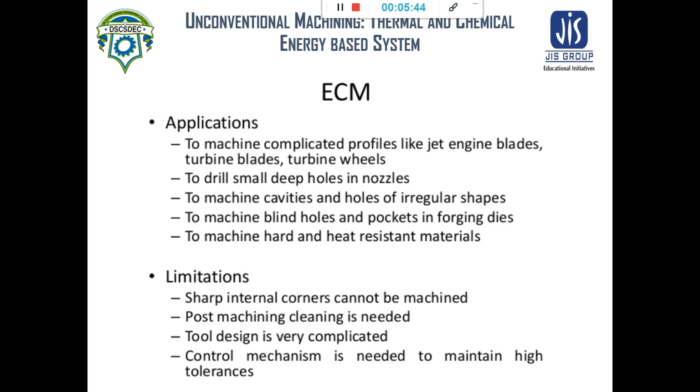Now, the limitations. Sharp internal corners cannot be machined using this process. Post-machining cleaning is needed. Tool design is very complicated. A control mechanism is needed to maintain high tolerance.